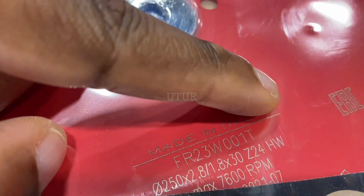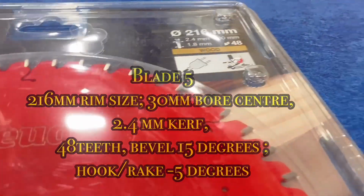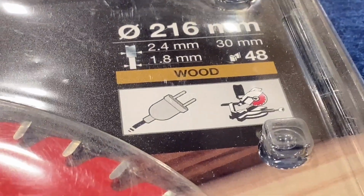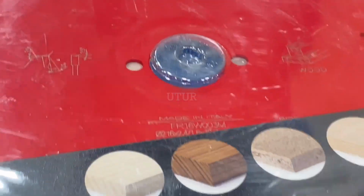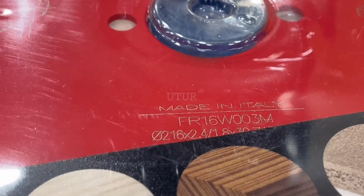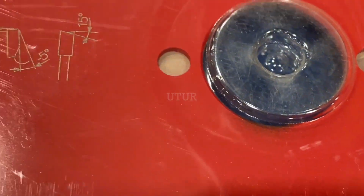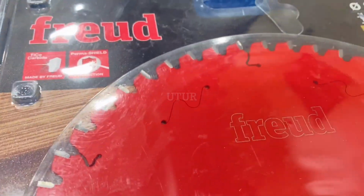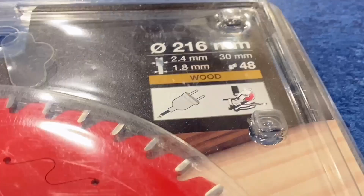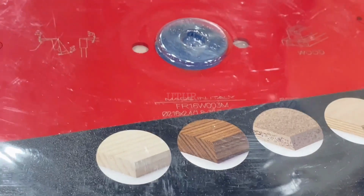The next quality blade has got a 216mm rim size, a 2.4 kerf, 48 teeth and a 30mm center bore, with a -5 hook angle and a bevel of 15 degrees. The negative hook angle connotes that this type of blade would preferably be used on a table saw, and the 15-degree bevel connotes an all-purpose ripping and cross-cutting blade with an alternate top bevel configuration.